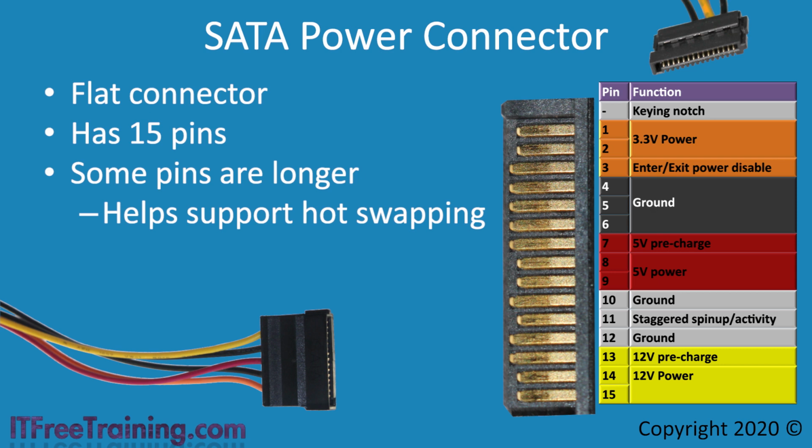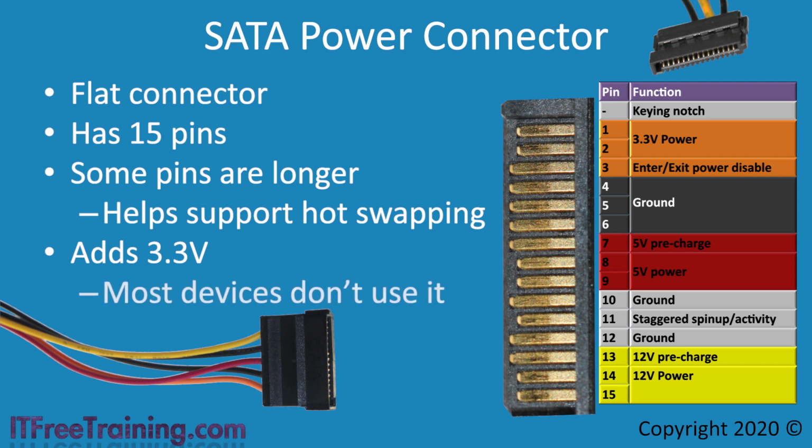The SATA power connector adds 3.3 volts of power. Although the SATA power connector is designed to be compatible with the Molex connector, the 3.3 volt power is not available in the Molex connector. In the real world, this is generally not a problem because not many devices use the 3.3 voltage.